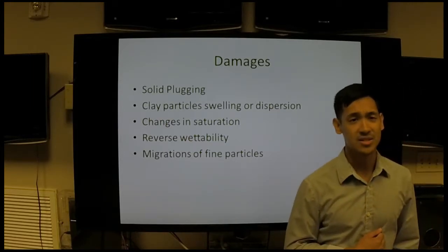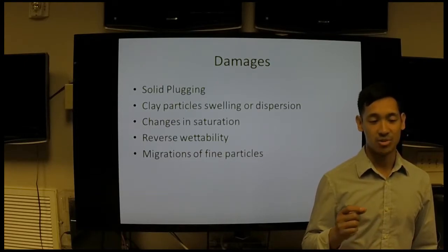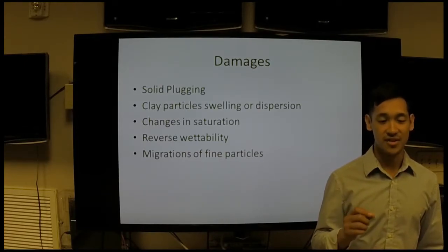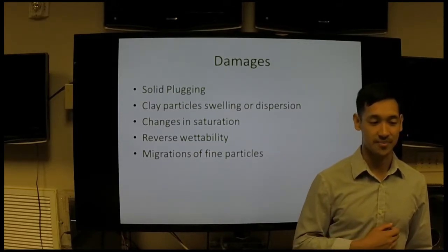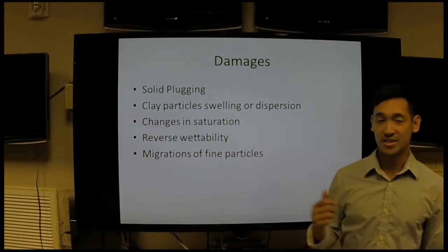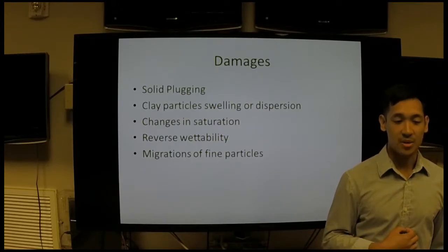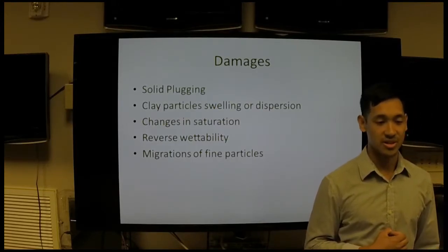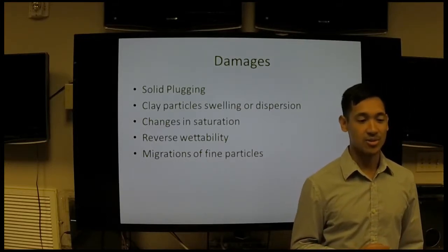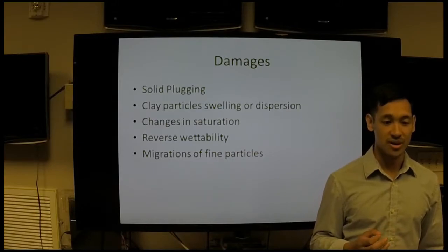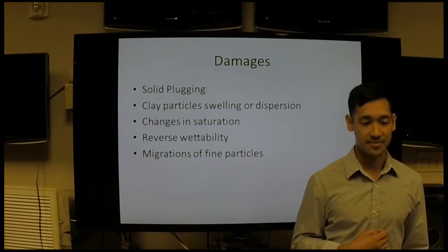Solid plugging. This is when pore throats are plugged in the rock matrix, which is forced by the mud filtrate. These very small fine particles are dislodged by the filtrate within the matrix of the rock. Clay particles, which is very similar to the migration of fine particles, as you can see here, is a common problem in sandstone, which contains water-sensitive clay. When fresh water filtrate invades the reservoir rock, it will cause the clay to swell or even move, reducing the total pore diameter in the area.